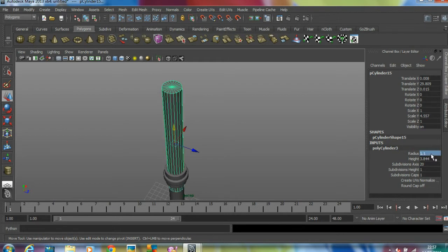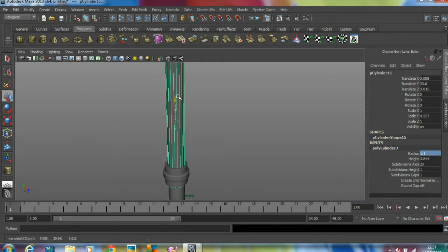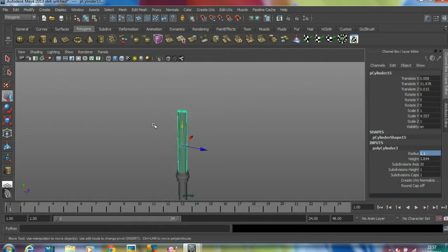Let this, yeah. Here this one, I'll just use this and a little bit of curve here, turn. So I'll just change it to 8. Caps, I don't need any caps, but I need some height segments because I need to bend it. So I'll go for some 5.